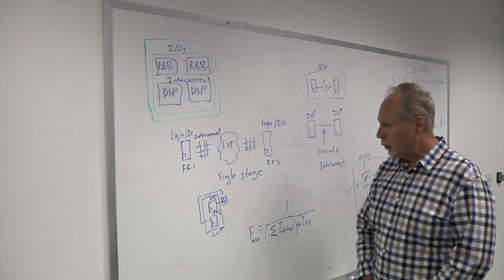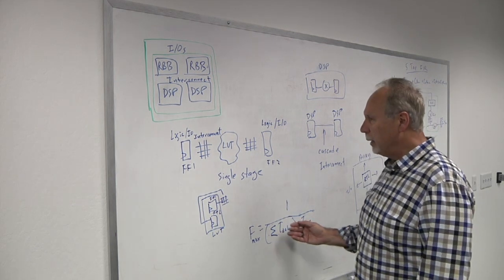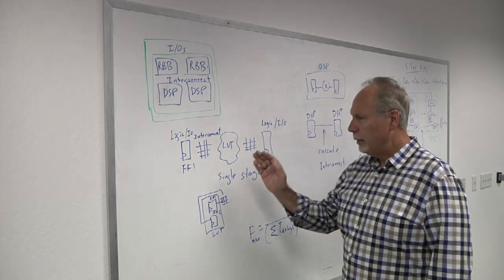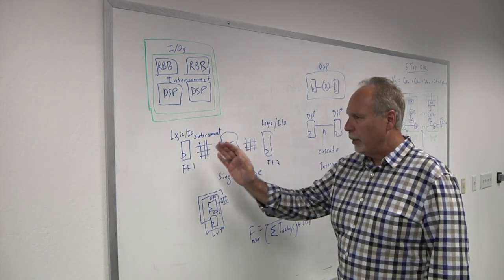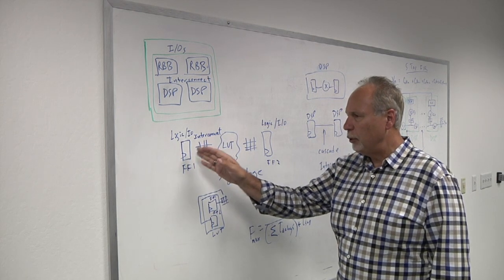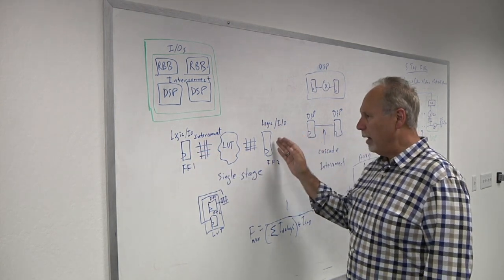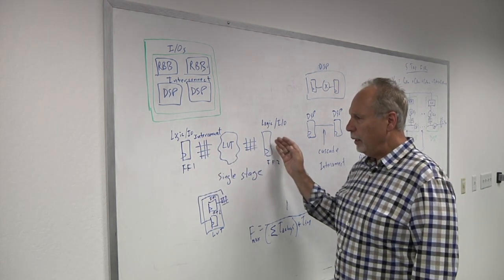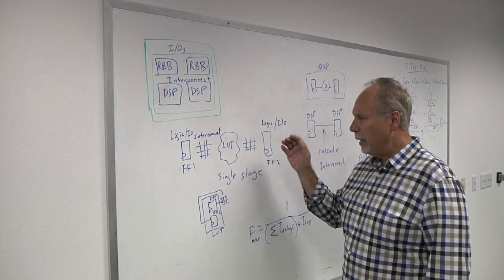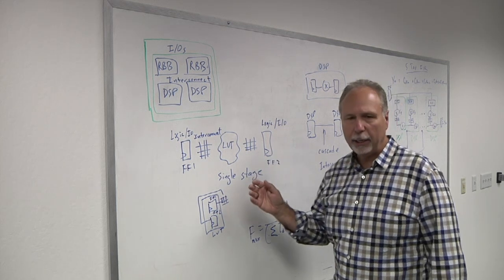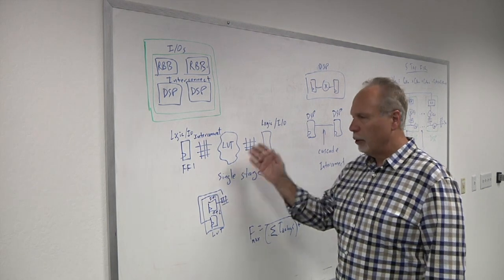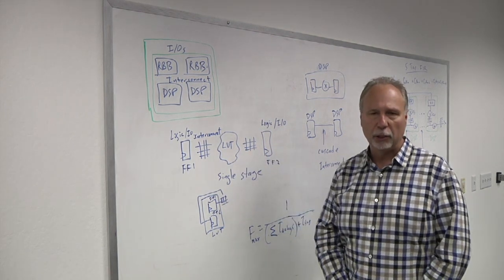So, can you give us more detail in terms of what are some of the specific areas that contribute to the delays? So when you look at the total delays, you're really looking at a flop to flop delay. A clock is coming to one flip-flop and arriving at another flip-flop, and the signal propagating through the fabric, through logic, and with the setup time, what is the worst case timing path. So that's what we call single stage logic. How fast is a single stage logic?